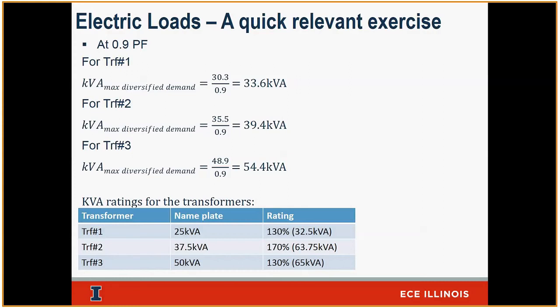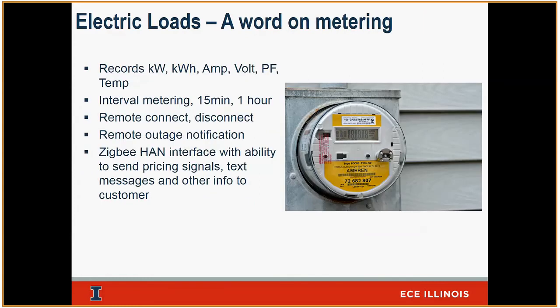Right? When trying to manage all the transformers that we've got, millions of transformers, what is the life expectancy on those? And you can start actually drawing heat maps. Some of the sophisticated software tools that we've got today can do this analysis for you. You don't have to go plug it in by hand. So we'll talk about AMI and getting the data in real time. So you can start calculating in real time what is the life expectancy of your transformer and get some kind of a heat map per circuit that says, okay, this is red, these transformers are in danger, this is green, transformers are doing fine.